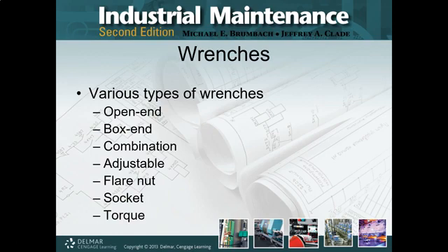And if it is very specific, your technical manual will tell you the steps that you need. The first step, you torque to this. Second step, you torque to that. Third, fourth. You just literally follow along with what the manual says, and away you go. So, torque wrenches. There's different types. I've got specifically one type, and that is the dial. So I'll show you that one, like I said, once again in lab.